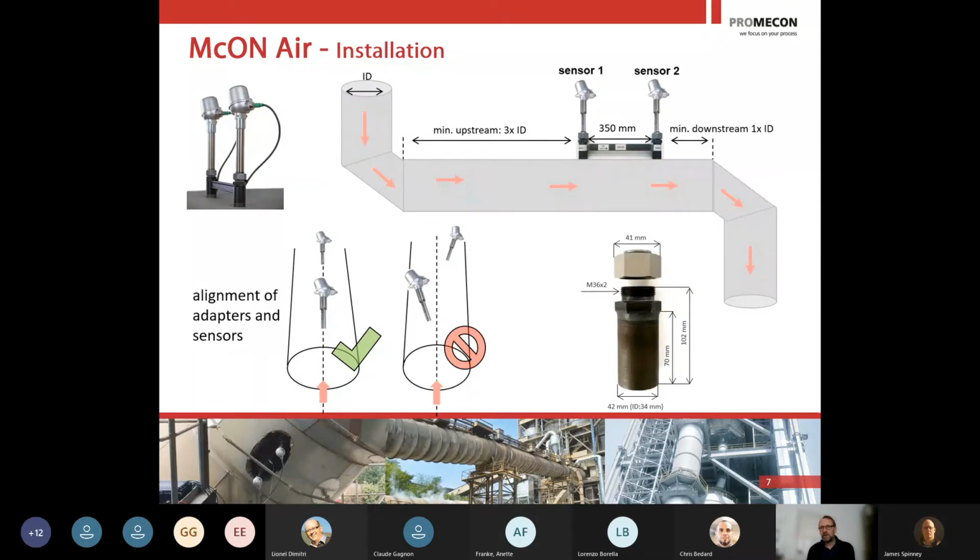This beam is basically to ensure that the sensors, or the antennas which are inside of the process, are aligned parallel, because you can probably imagine if the antennas are not parallel and the distance is not controlled or certified, then of course you have an uncertain distance to calculate your flow velocity.